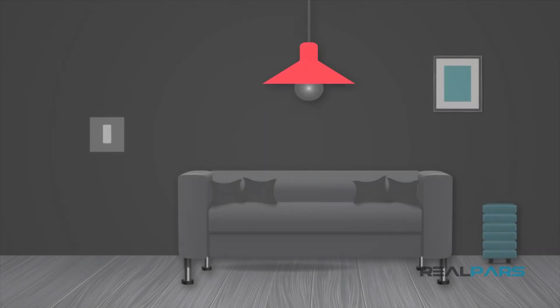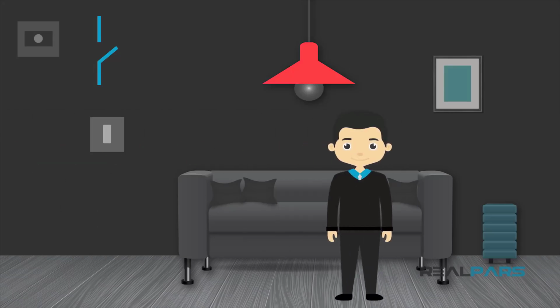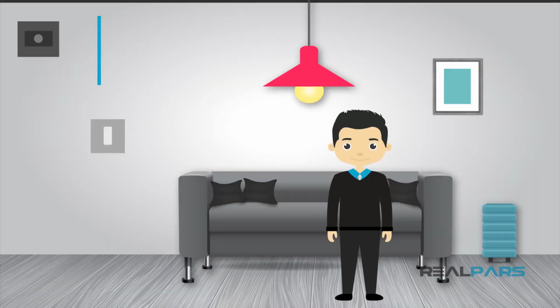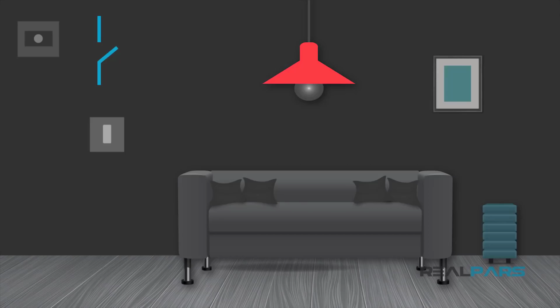Now, let's say that instead of the wall switch, I'll install a sensor in that room. This sensor has a simple open contact within it, just like a normal switch. The way that this sensor works is that it always looks into the room, and when it sees someone entering the room, the open contact is going to be closed, and following that, the light's going to turn on automatically. When the person leaves the room and there's nobody there, the contact will be open again, and this time the light will be turned off automatically.